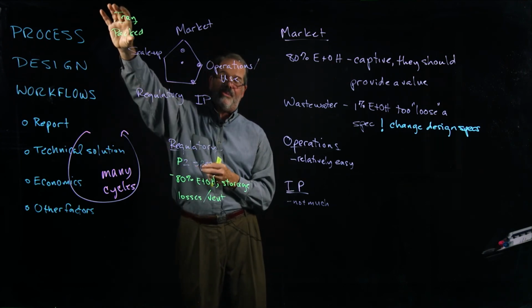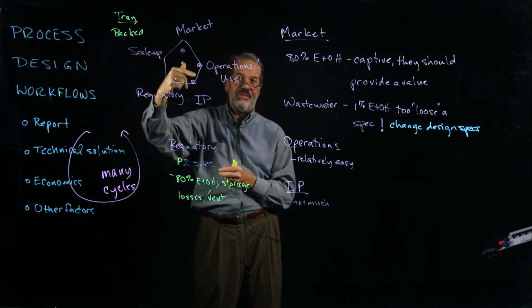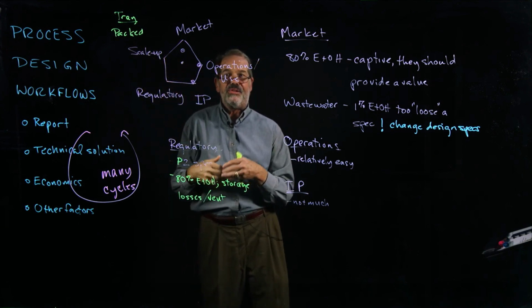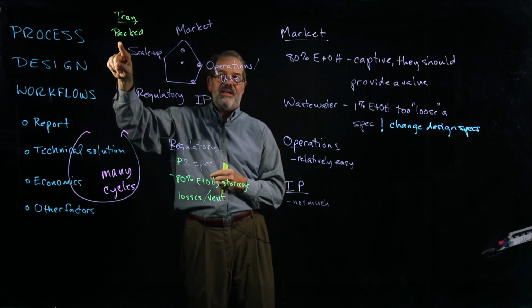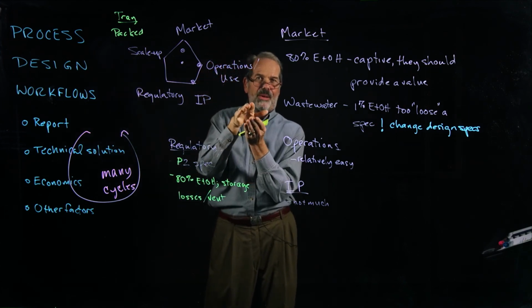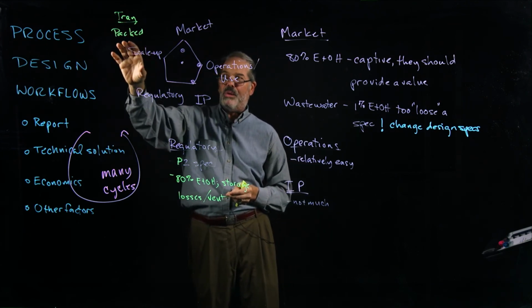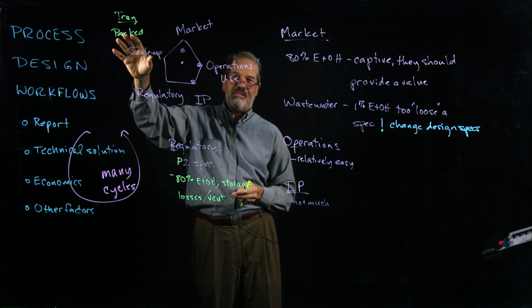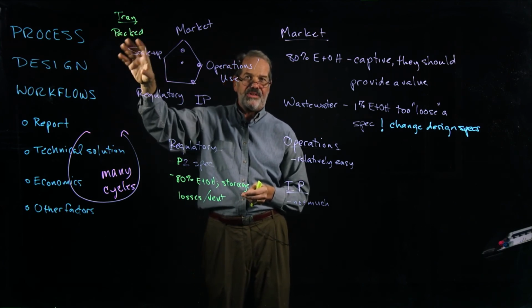A tray column sometimes can be turned up and down by 30 to 50% in terms of the column feed and still generate a good product. The packed column usually is less flexible. That is, it's got a narrower operating range, and we need to be careful about what the total amount of material is that's coming to the process and how much we can scale up and scale down and still get good performance.